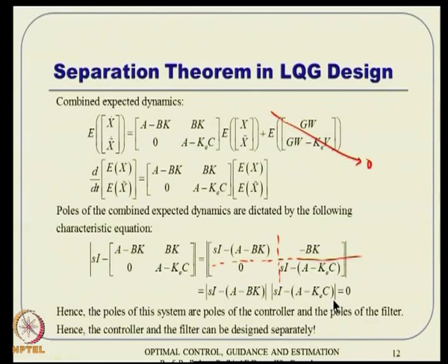It is a big achievement because that gives a lot of confidence to the people working in this domain that things can never go wrong if I implement it this way, of course, provided both happen in the framework of a linear time invariant system. A small comment: we have also seen that many people have implemented the Kalman filter in a nonlinear framework, because that is the way to implement an EKF essentially. So, even if the controller happens to be in the linear framework, the estimator always happens to be in the nonlinear framework typically.